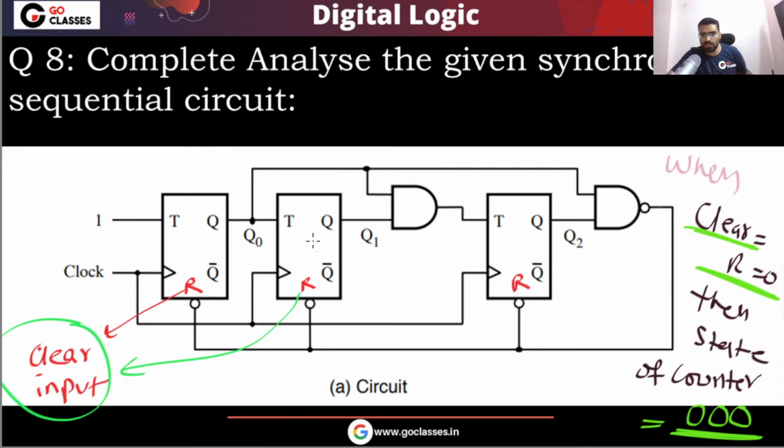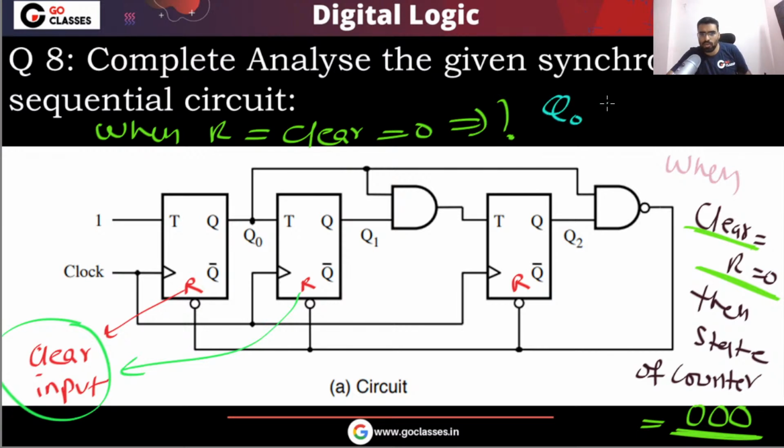So when will the state of the counter become 0, 0, 0? When clear becomes 0, tell me. Clear is equal to R, and clear will become 0 when Q0 and Q2 bar... Remember this R. If you understand what this R is, I can say it is basically Q0 and Q2.